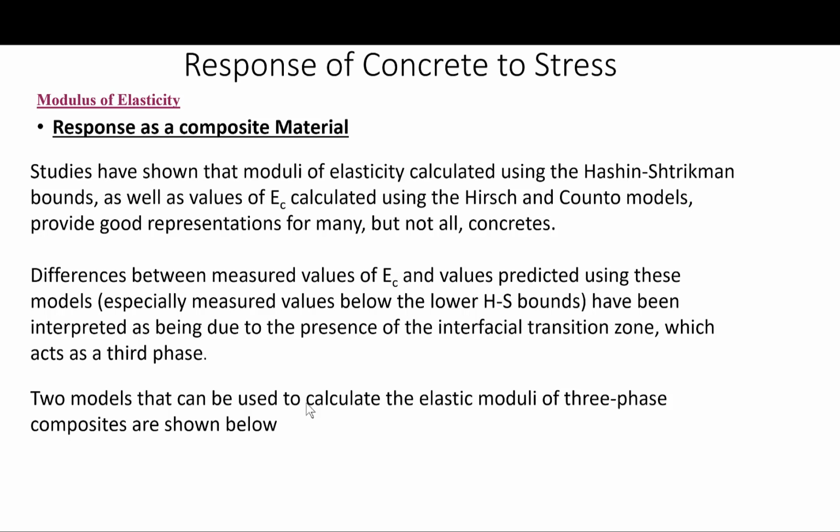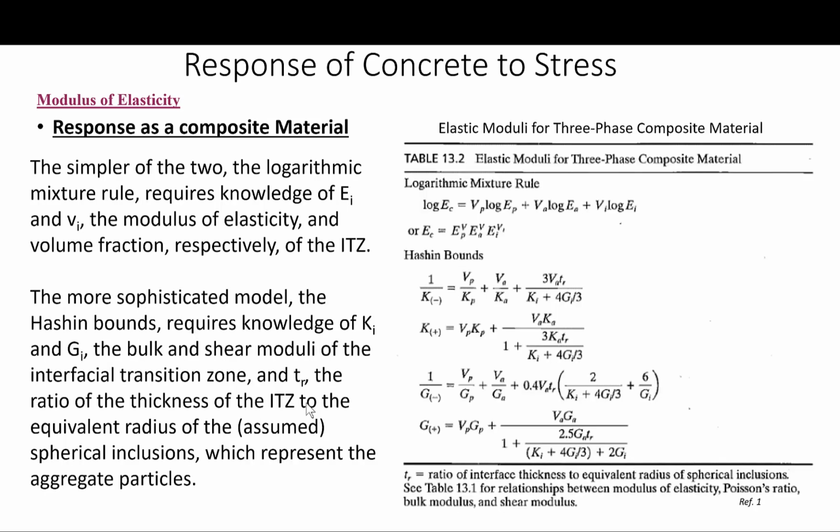So the two models can be used to calculate the elastic moduli of three-phase composites, as shown in the table on this slide. The simpler of these two, which is the logarithmic mixture rule, requires knowledge of E sub I and V sub I, which are the modulus of elasticity and the volume fraction of the ITZ.